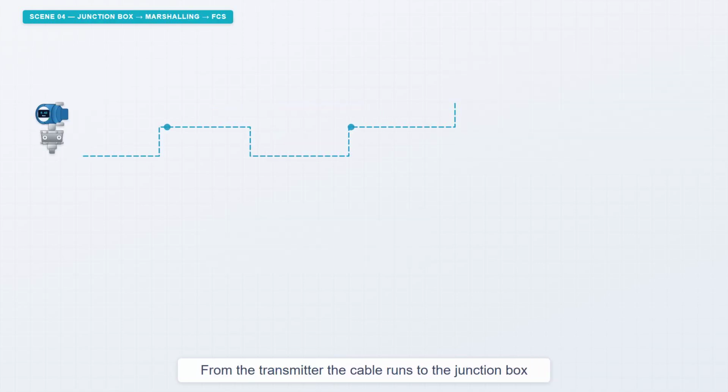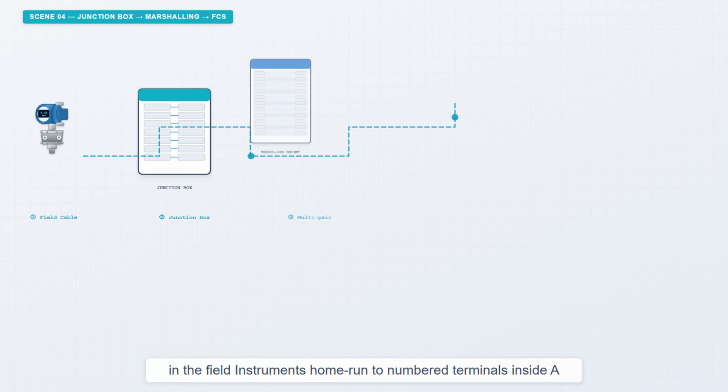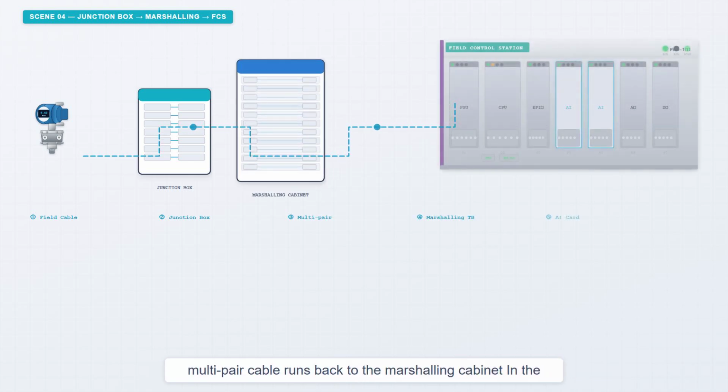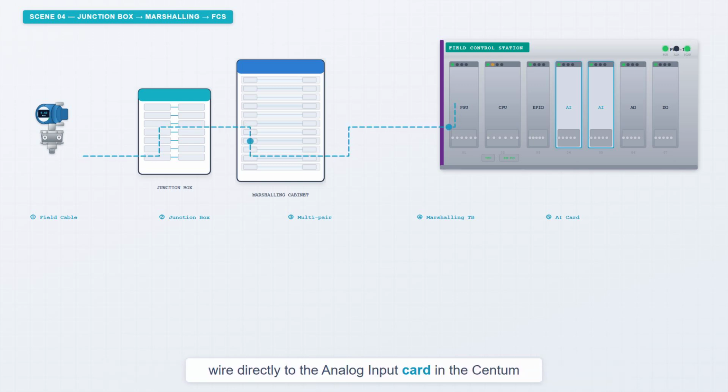From the transmitter, the cable runs to the junction box in the field. Instruments home run to numbered terminals inside. A multi-pair cable runs back to the marshalling cabinet. In the marshalling cabinet, individual pairs connect to terminal blocks. Those terminals wire directly to the analog input card in the Centum VP FCS.